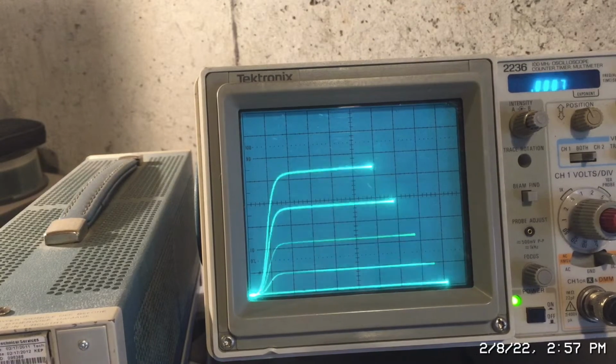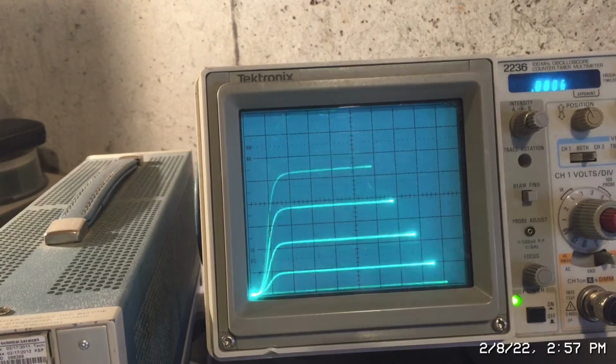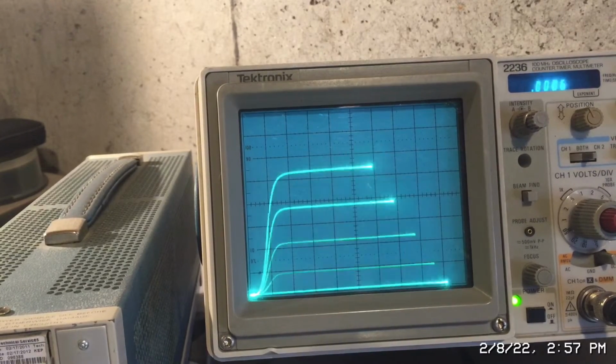But what do we have now? You can actually see a dramatic difference between these two. And again, they're both Fairchild, both the same manufacturer. The variation is caused by the doping process and the concentration of semiconductor material, which is not accurately controlled the way you might think.